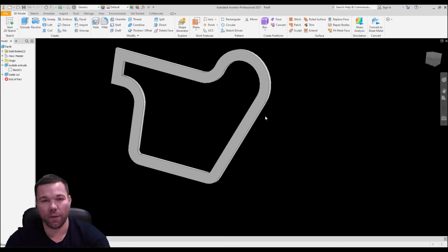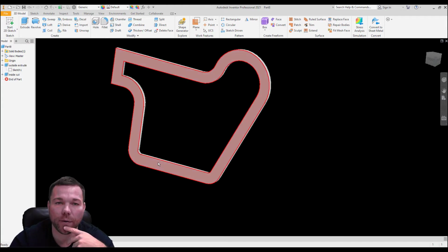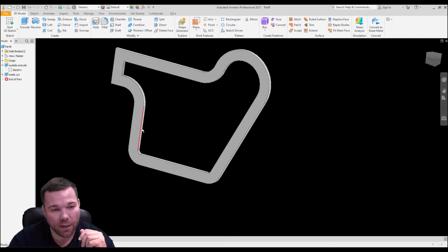And you can see there that the outside looks correct. So it did make it the right shape, and of course it continued the offset to make sure that it stayed 15 millimeter. If I had just drawn this in here without doing the offset, this bottom part would be very thick on the gasket, so it wouldn't have updated the inside to be 15 millimeter away. It would just be whatever it was dimensioned to.